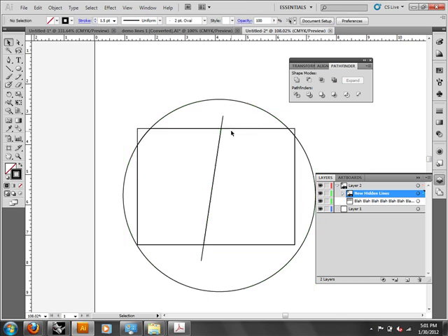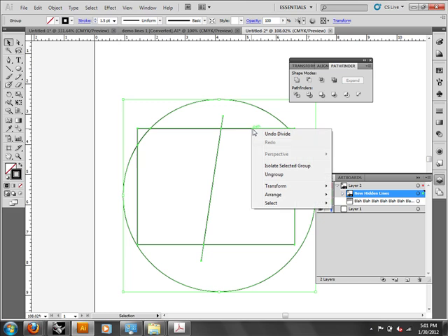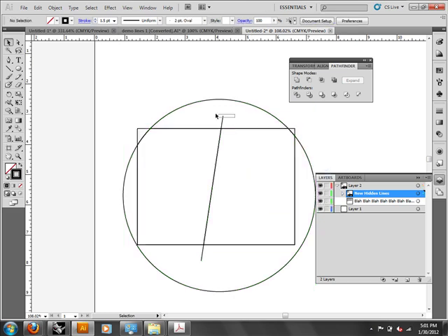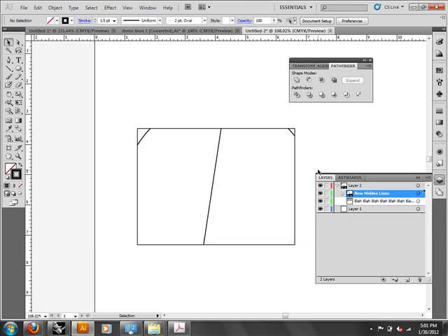and let me see if I think it makes a group of these. Yeah, it makes a group, so you ungroup it, and then you can go in and actually get rid of these pieces. Okay, so Pathfinder, like divide. Trim doesn't work the way that you think it's going to work in Pathfinder. You can experiment with all the different Pathfinder things.